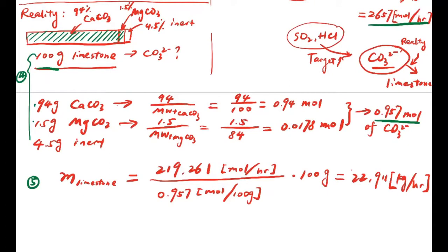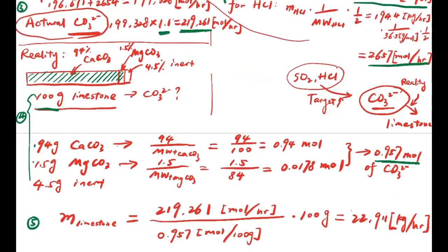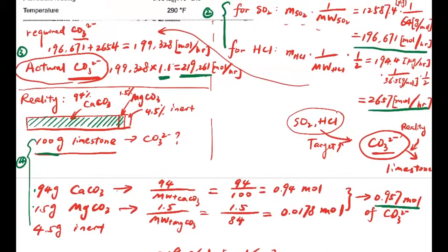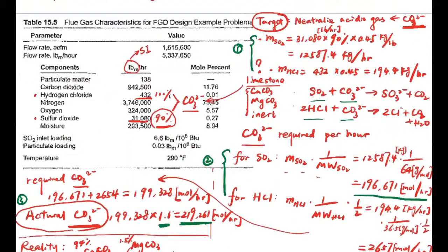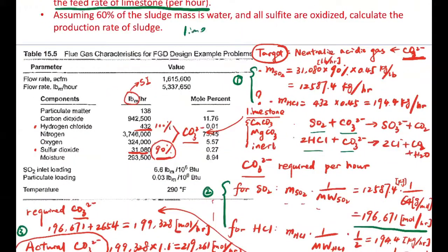And I would say that you're going to use the same method for your dry sorbent injection. Let's say we're introducing trona or lime into the system, right? We know that the lime is not pure calcium oxide, so there's always some other chemical species, for example, sodium oxide or sodium carbonate.